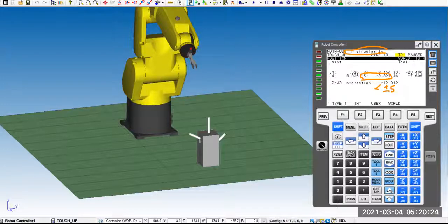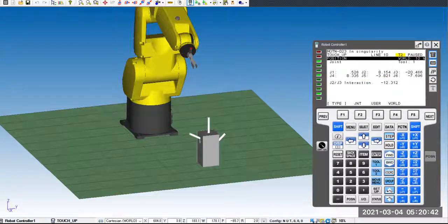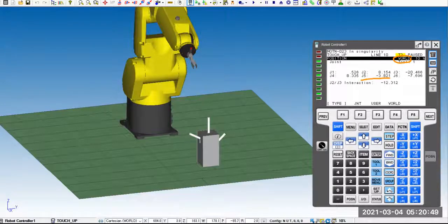All right, this is not a video to talk about singularity. You can Google, you can check, you can read my lecture slide. All right, so it's a fault when you jog in world. The problem is J5 is close to 0 degree, right? To solve that problem, remember that we have to switch to joint coordinate. The problem is J5, so we have to fix J5, right?